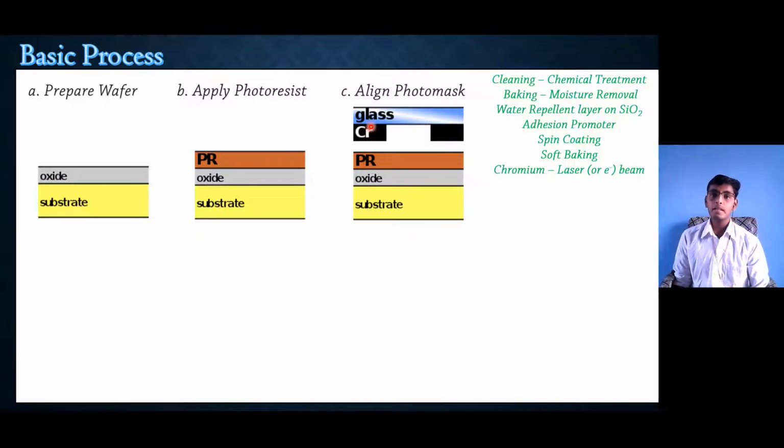Preparing the photomask is also another lithography process, but the difference is that this lithography process need not be complicated, because the size of the mask is comparatively larger than the size of the chip that we require. So a simple computerized printing can do it. The printing process we use is a laser beam or an electron beam.